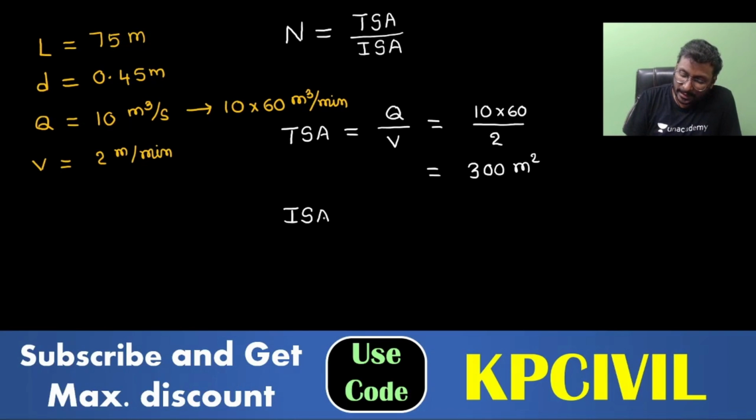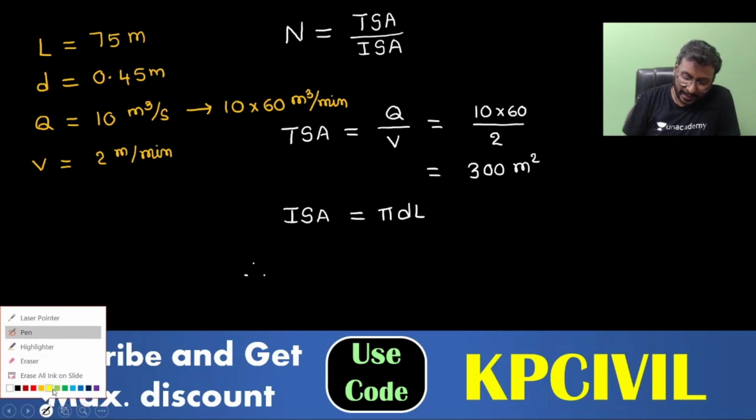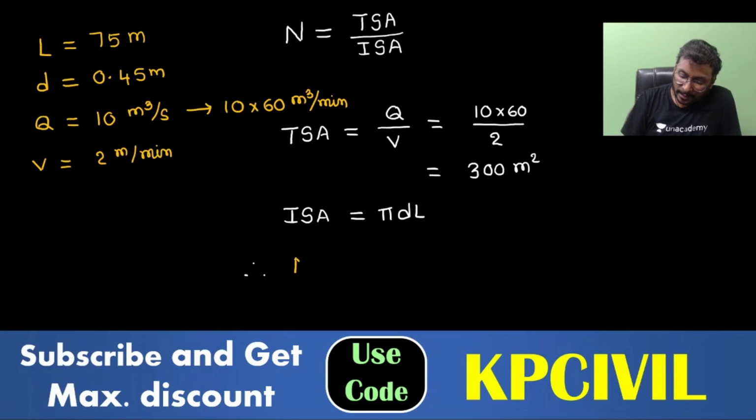Individual surface area is pi dl, because it is a cylindrical cotton bag. So we will solve for N, number of cotton bags required. Total surface area 300, individual surface area pi into 0.45 into 7.5.